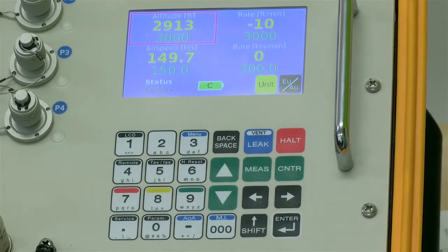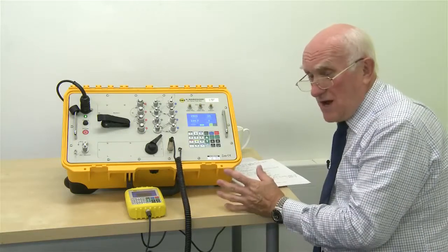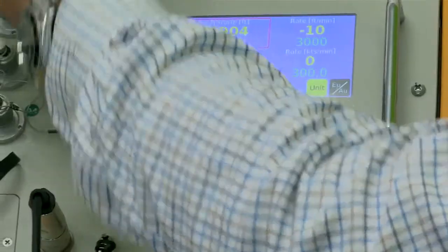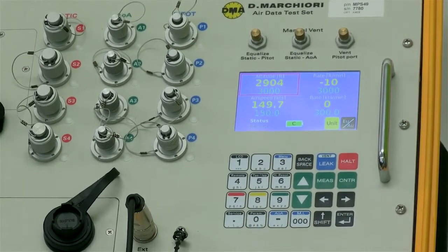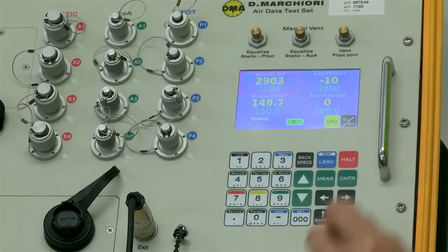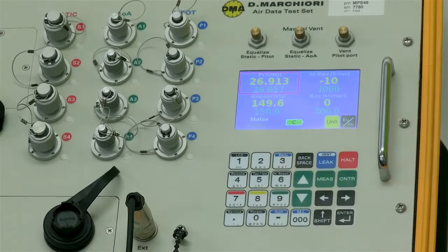The 49, the 3-channel instrument that also has angle of attack, you have a different situation in that you can now go in and address the angle of attack capability. So we'll do that now. Okay, just to show you how it works on the angle of attack, remember we've now got that other row, that 3rd channel. We could go, just for the moment, to altitude, and I'm going to go to engineering units, because with the angle of attack you're going to be putting in as demand values pressure values, not true angles in degrees.